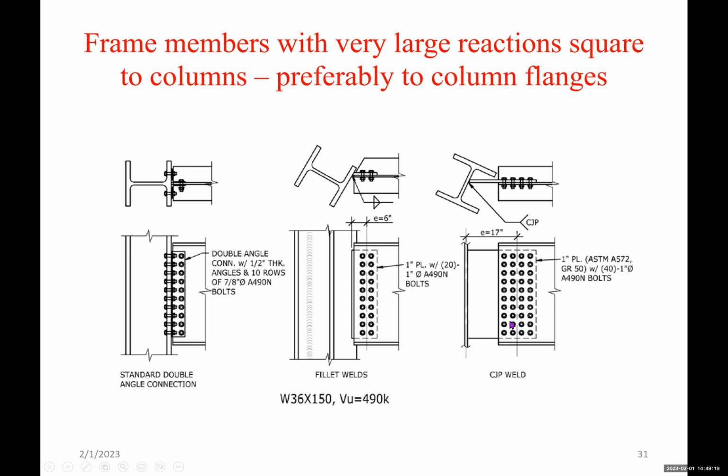Look how many bolts we need, and the longer the plate, and of course, considering the forces and the moment and the connection here, the moment that will end up in the web of the column, the design is getting more and more difficult. Yeah, and of course the constructability as well.